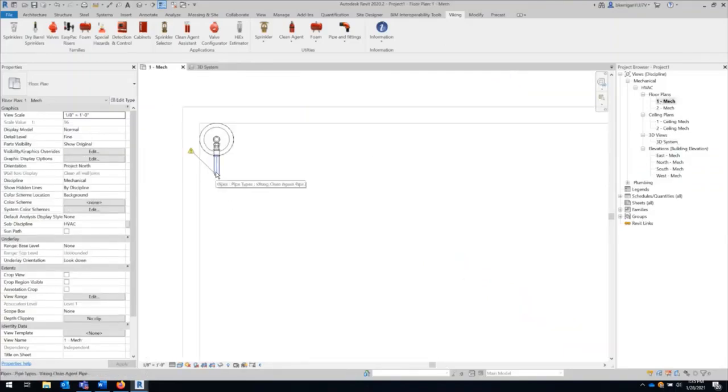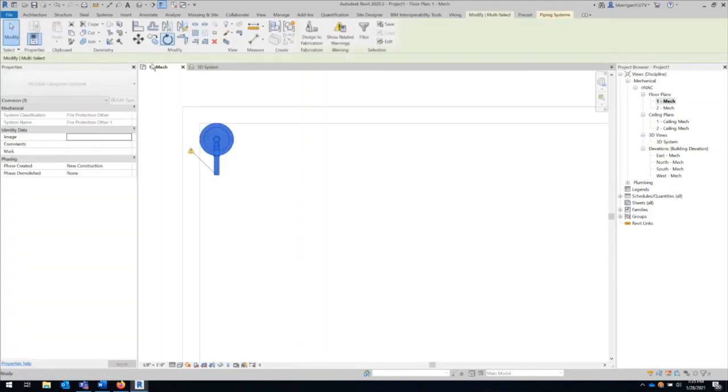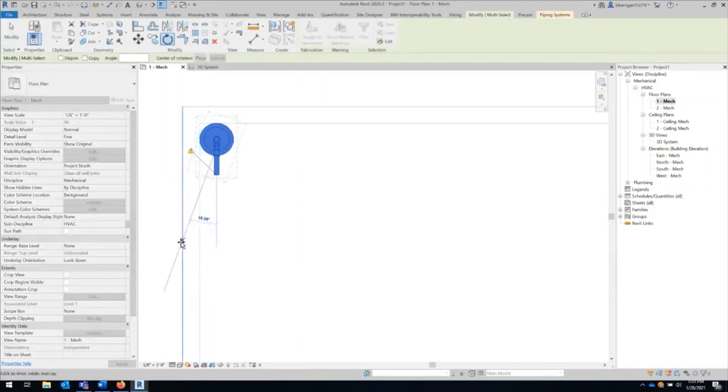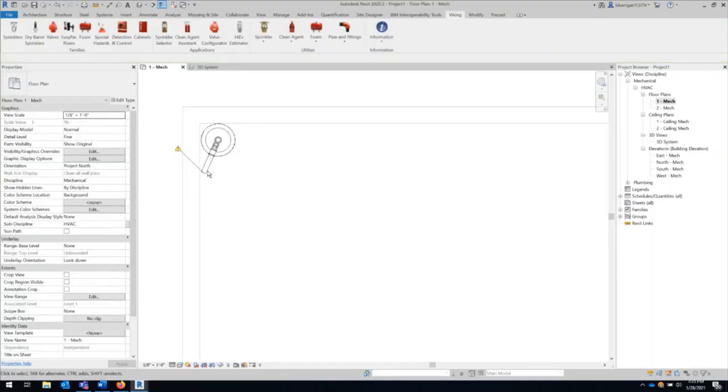Something you will usually see is that this container and that pipe will actually be angled back towards the wall, and you're mostly going to do this so that you have something to secure that piping to. So you can kind of rotate it over, nudge it back over towards the wall. Don't need to be super exact there, but you can imagine you're running over the wall, securing, running up to the ceiling, and then running out to any nozzles.